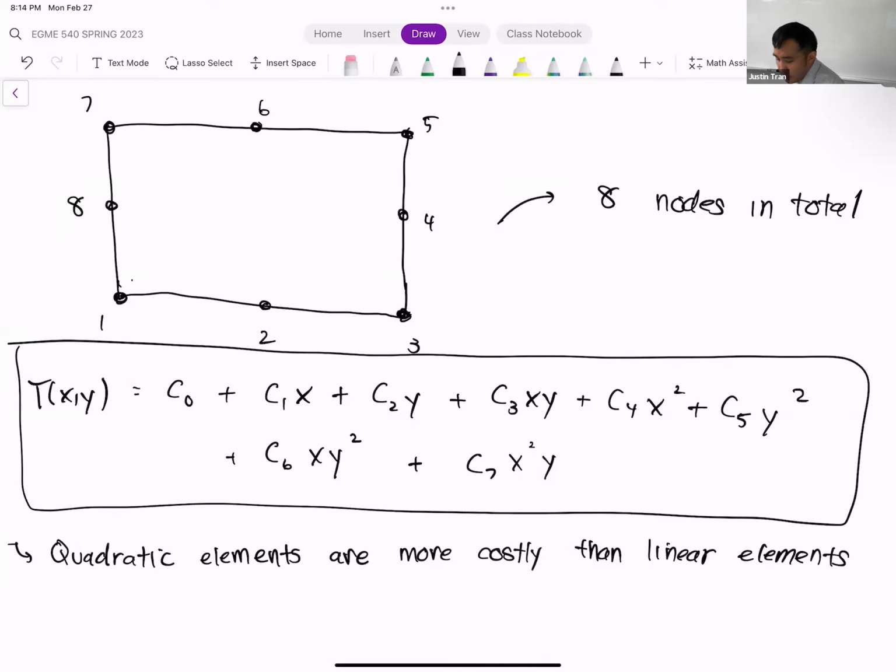as you've already seen for rectangular elements, for hexahedrons, sometimes it's really hard, if not impossible, to fill a space with hexahedrons. Once you start getting beyond that, it gets to be almost impossible to do a mesh with a pentagon or a hexagon, unless you have a very constrained, very simple problem. It's just not practical.